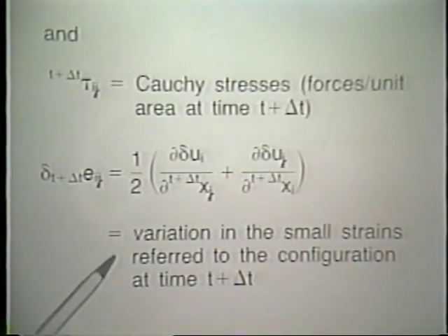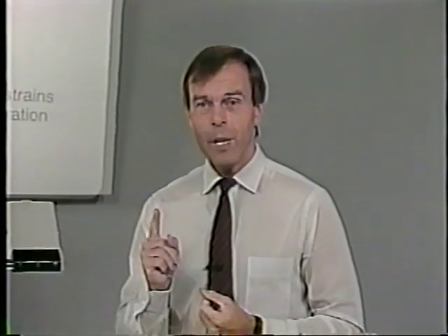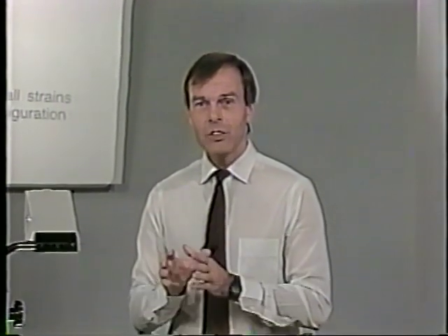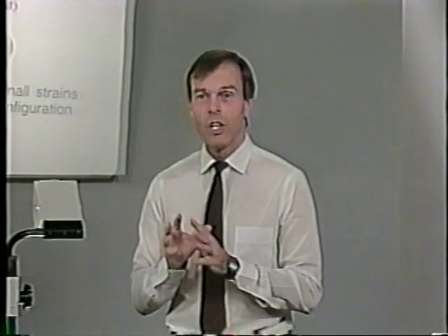And that is spelled out down here, that we're using a variation in the small strains referred to the configuration at time t plus delta t. So really, if you are familiar with the principle of virtual work as applied in infinitesimal displacement analysis, then you recognize that the principle of virtual work now applied to large deformation analysis, large displacement analysis, is quite the same, except that we are applying it to the current geometry, the current configuration of the body.